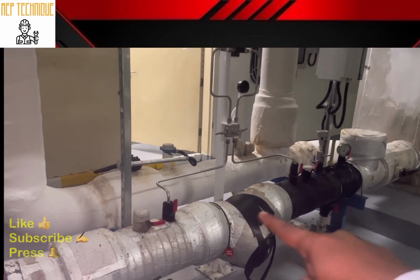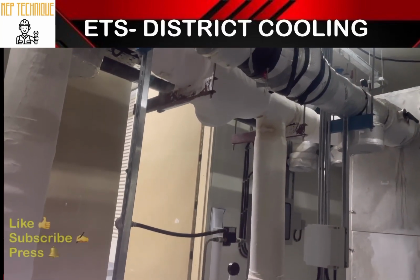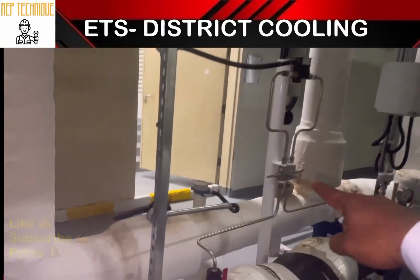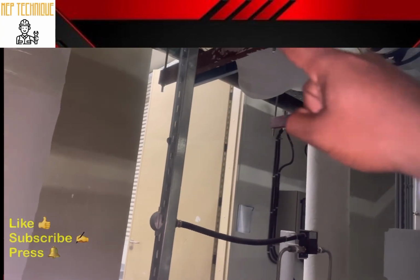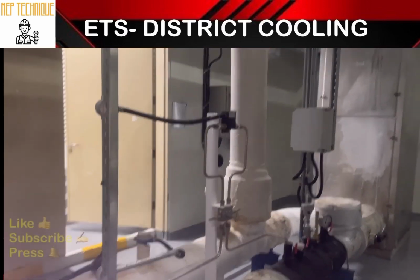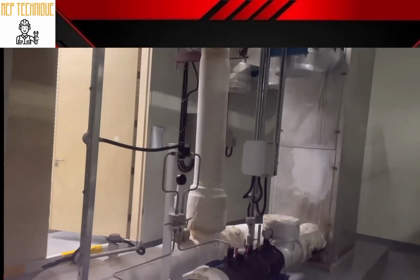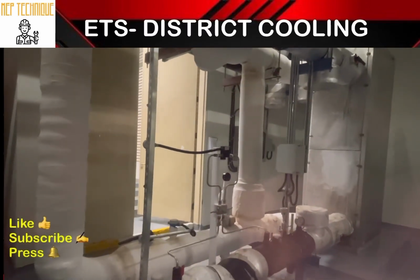One is the primary line. This is the primary circuit, which is connected with the distribution company, which may be Tabreed in Abu Dhabi, Emicool in Dubai. This is the white line which is insulated, and it is connected with our building. The secondary line is connected with our building's units such as FCU, AHU, FHU, whatever is available in our building. Now we will start with the chilled water distribution.